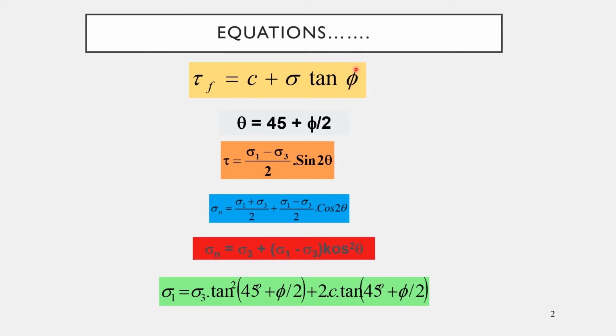But bear in mind, as we discussed, not necessarily every type of soil will have both parameters. If it is cohesive soil, the shear strength relies on cohesion, in which the friction angle is assumed to be 0. On the other hand, if the type of soil is cohesionless soil, the shear strength depends mainly on the friction angle, in which C is assumed equal to 0.